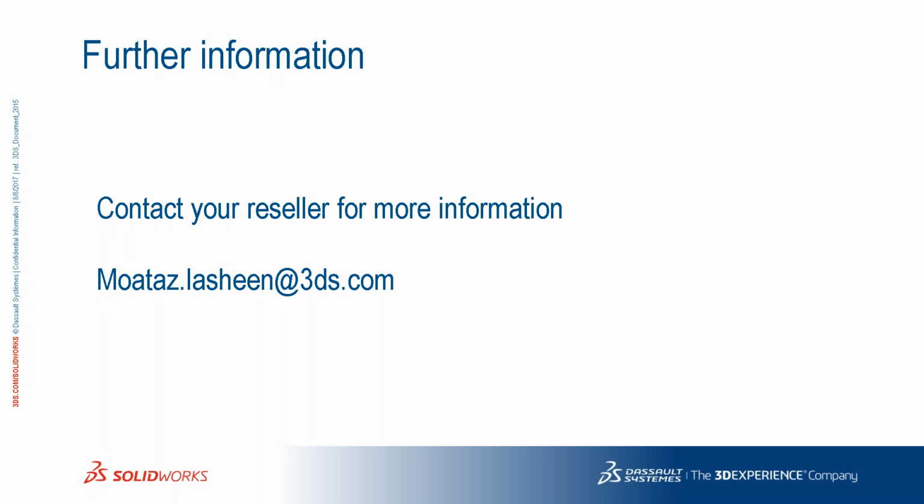And not only that, in the initial stage, when you just need to understand what the behavior of the flow will be, and you don't want to spend much time in the processing phase, in this case we can advise you to go with two-dimension just to indicate what the result will be. However, if you find from your initial parameters that everything is fine, you can go directly with the 3D meshing. Hopefully that answered the question.